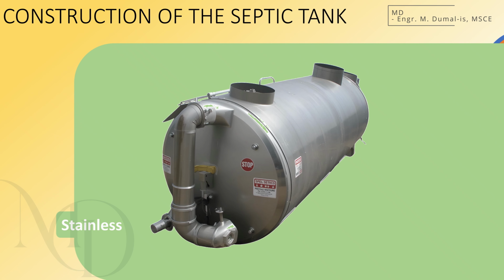Stainless steel septic tanks are uncommon for homes but worth mentioning. They are strong, resist corrosion better than ordinary steel, and can last a long time if properly maintained. The trade-offs are their high price, susceptibility to pitting corrosion in aggressive soils or coastal areas, and the fact that they are rarely available for residential projects.